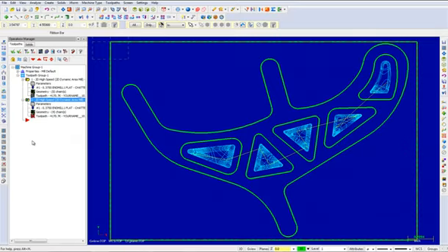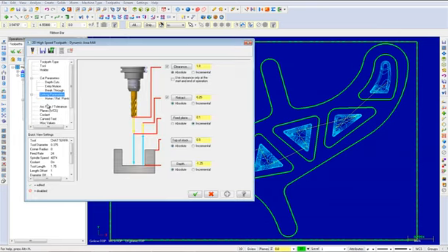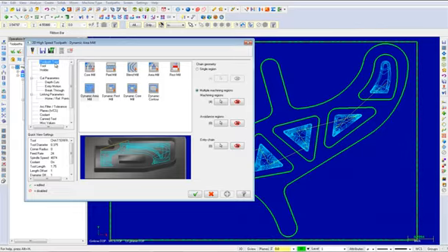We will now change the toolpath parameters to generate a rest mill operation. Select Parameters in Operation Number 2. From the Tree View list, select the toolpath type page. Choose the dynamic rest mill as shown. We will now select a 1/8 flat end mill from the library and set the tool parameters.